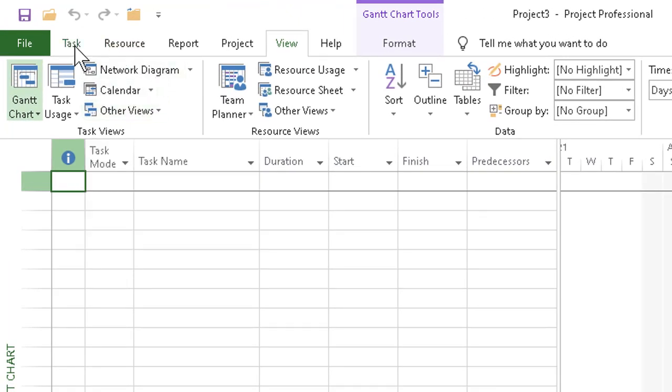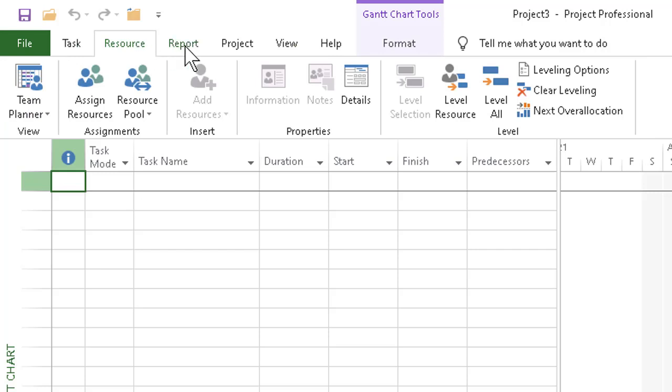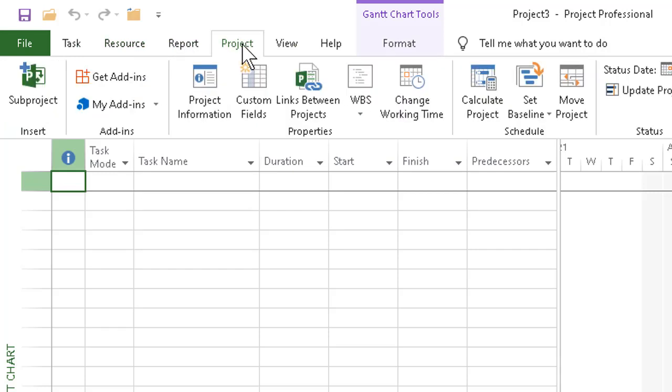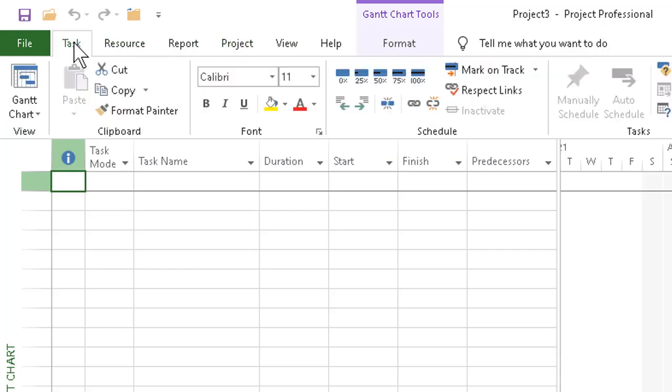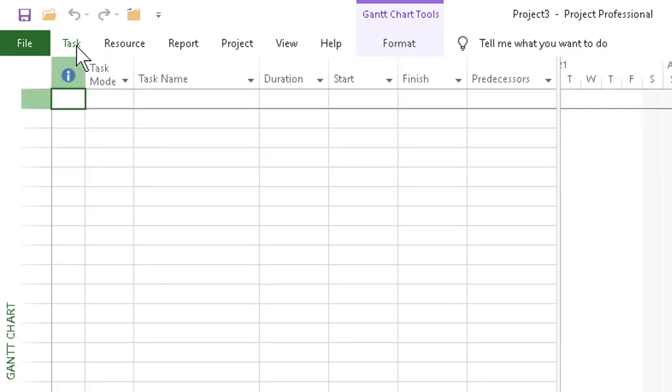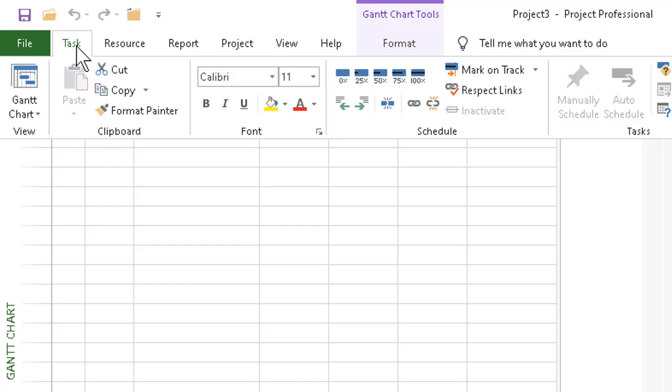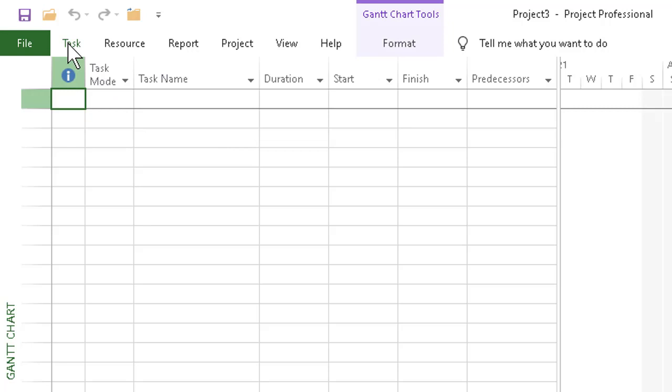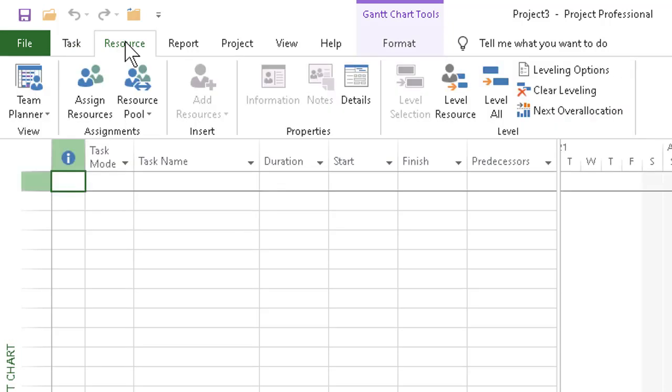If we click on any of the ribbon tabs, we are immediately taken to that section of the ribbon. We can therefore get to the various commands we want very easily. If we double-click a tab, the ribbon will collapse or fold up, whereupon a single click will open it temporarily. We can do whatever we need to do. The ribbon will then tuck itself back into storage. However, if we give any of the tabs another double click, the ribbon will lock open once again and allow us to continue working with it more easily.